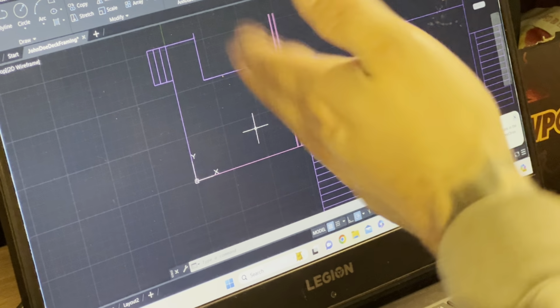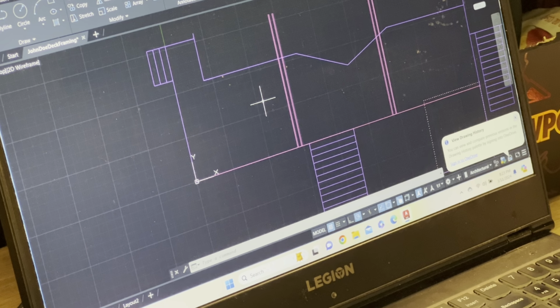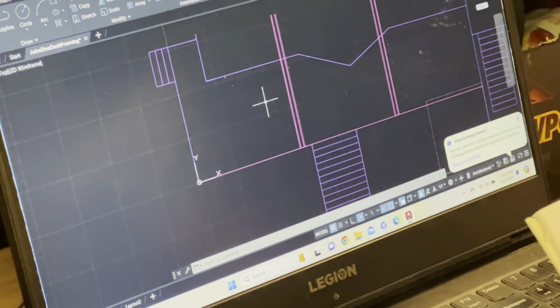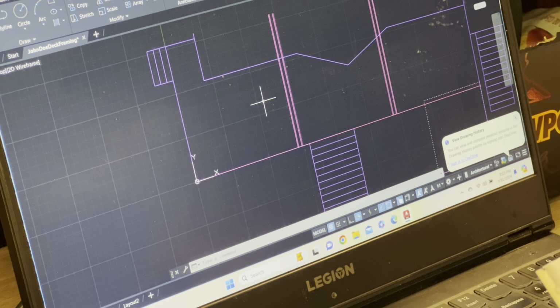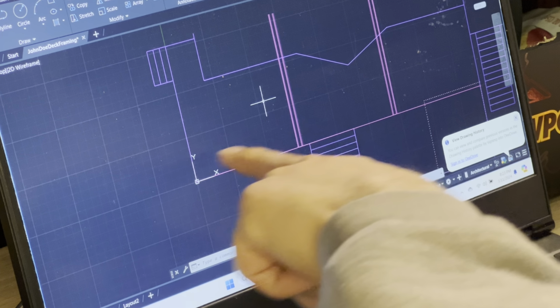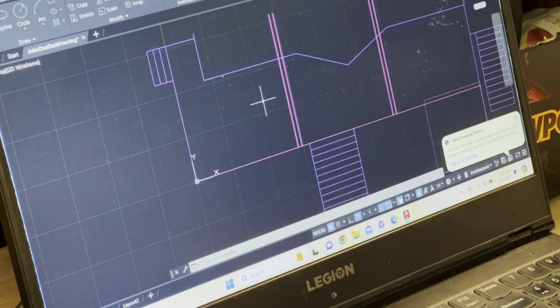Now I know that I'm going to frame this deck at 12 inches on center. So I already went through and calculated what I wanted and wrote it down up here. I'm going to have 24-inch footings, 6x10 beams, and 6x6 posts, and I'm going to divide my beam distances here to get whatever's closest to 6 feet or under.